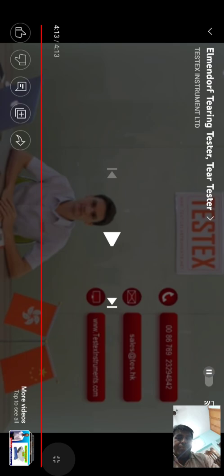So that is about tearing strength. So I think we are done with today's class. So far we have studied breaking strength and tearing strength, and in the breaking strength we have seen some video online at the end, and in the tearing strength I have shown you two videos, one about the Elmendorf tear strength tester, which is an ASTM standard D5587, and some of the standards are D1424.